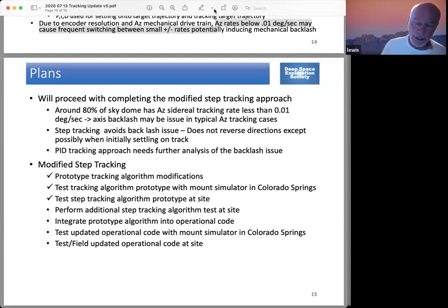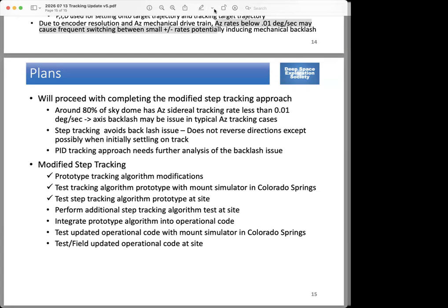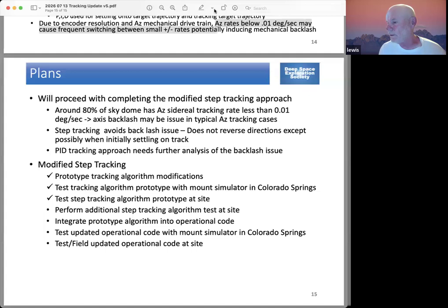So it's running many times a second. And then it's controlling the rate of the motor at, I think, 8 kilohertz. It obtains position feedback from the resolver in the motor.